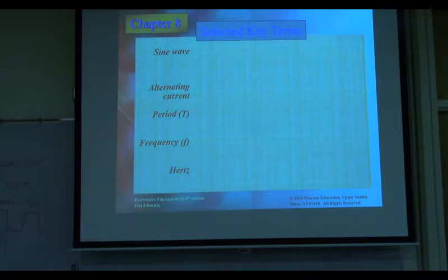So this is called a pseudo sine wave. If a product says, okay, we emphasize a pure sine wave, that means it's this one, just to distinguish it from this one. It means the quality of the sine wave is better. So I guess that would be the reason, like if you hook a microwave up to a pseudo sine wave. For a microwave, I believe you can use any. This one doesn't matter. But sometimes for a computer, or some equipment, you may want a high quality sine wave.